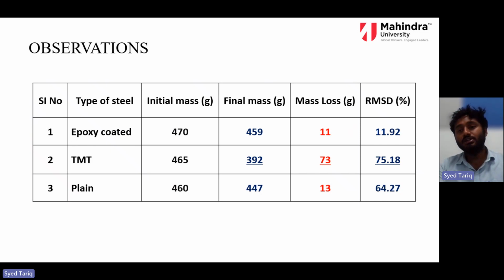Here you can see the RMSD value. RMSD is the root mean square deviation. It is nothing but the mean deviation in the structural peaks, taken from the healthy baseline signature to the topmost, the damage 38th hour signal. From this signal to this signal, how much is the deviation in that conductance signal? That analysis is done through statistical tools, and RMSD is one of those tools that I have chosen.